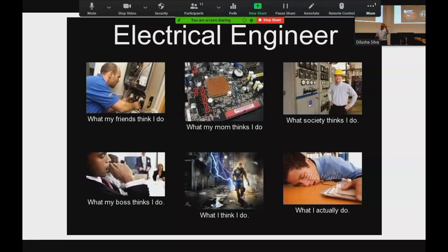Fundamentally, that might have a solid state relay in it, but at some point it has to break a 240 volt rated circuit. So you might come out of your relay board at 12 volt DC and drive a coil, and that coil then has a contactor that pulls your supply to your machinery in and out.